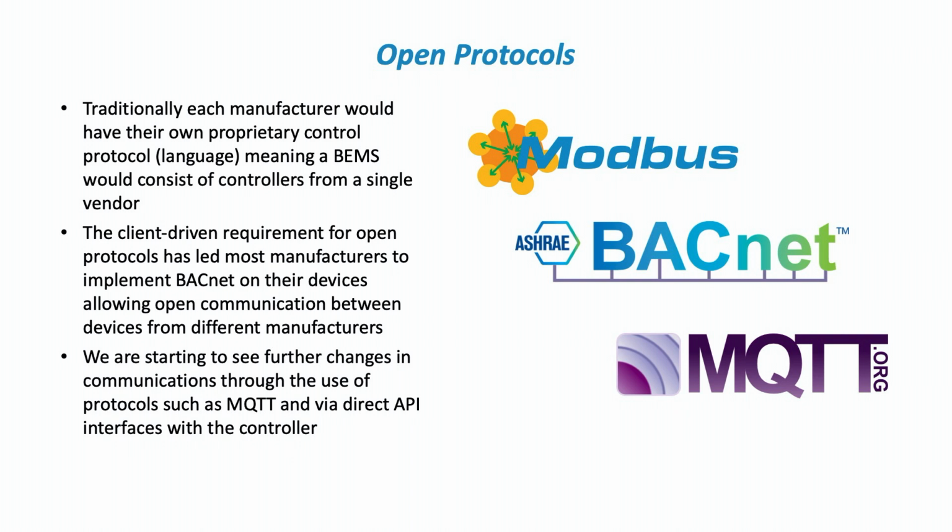There are two particular features of BACnet, the Who-Is and I-Am commands, which set it apart from so many other protocols. The Who-Is and I-Am commands mean that you can send out a broadcast message to a network asking Who-Is, what other BACnet devices are here, and you can receive an I-Am response from those other devices on the network.